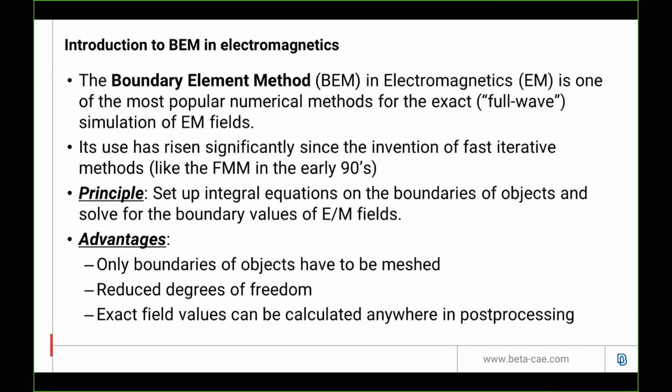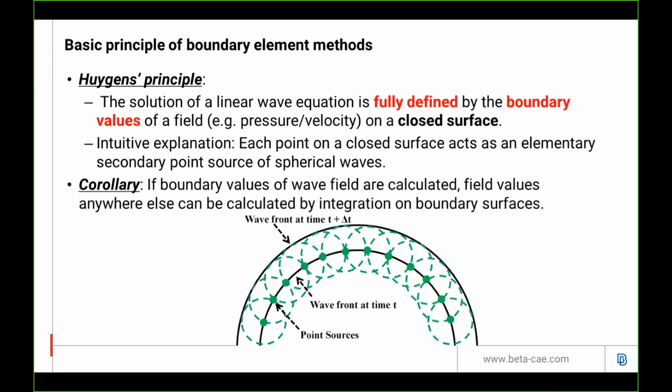The basic principle of boundary element methods is a very old principle called Huygens principle. This principle is represented best from the picture on the bottom of the slide, which tells us that the solution of a linear wave equation is fully defined by the boundary values of the field, for example, for an acoustic field, pressure or velocity, on a closed surface.